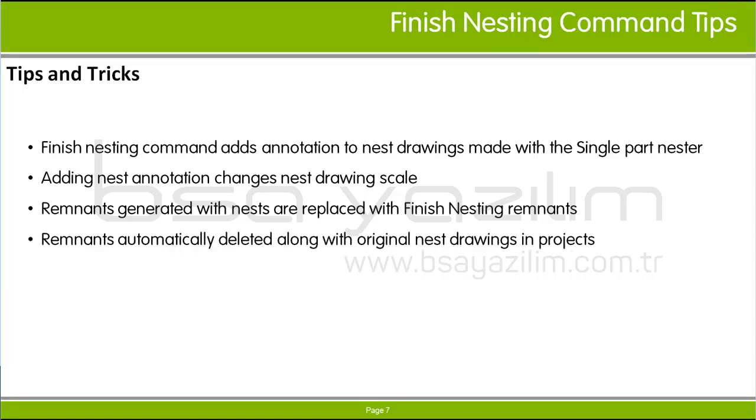If you delete a nest drawing from the list of nests in a project, Radan will delete the nest drawing file and any related remnants provided they haven't been released within the project yet. This Remnants tab will not be available if you are not licensed for true shape nesting.